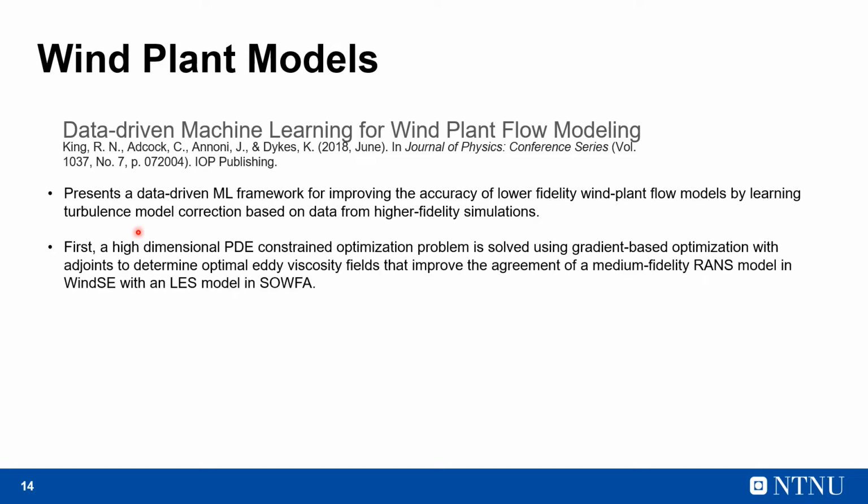First, a high-dimensional partial differential equation constrained optimization problem is solved using gradient-based optimization with adjoints to determine optimal eddy viscosity fields that improve the agreement of a medium fidelity Reynolds-averaged Navier-Stokes model in WindSE software with a large-eddy simulation model in SOWFA.